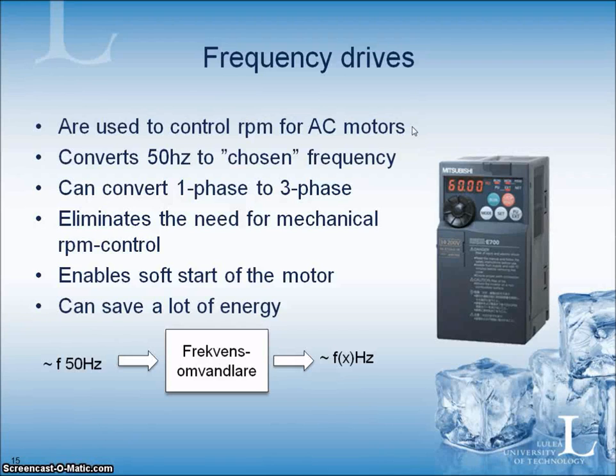It can convert one phase to three phase, and therefore it eliminates the need for mechanical RPM control like variators. It can also enable soft start of the motor, and it can save a lot of energy. So we have some power with 50 Hz that goes through the frequency converter, or frequency drive, and it ends up with the frequency of your choice.